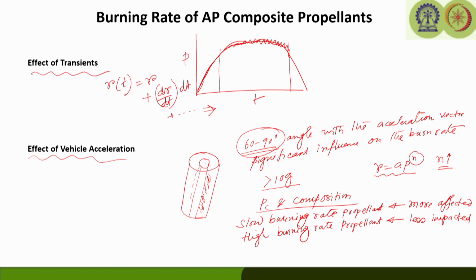However, since it is producing separate burning surface area, this will enhance the burn rate, but we need to be careful about whether this crack will lead to an increase of chamber pressure, which will in turn increase the burn rate, and which should not lead to failure of the motor.